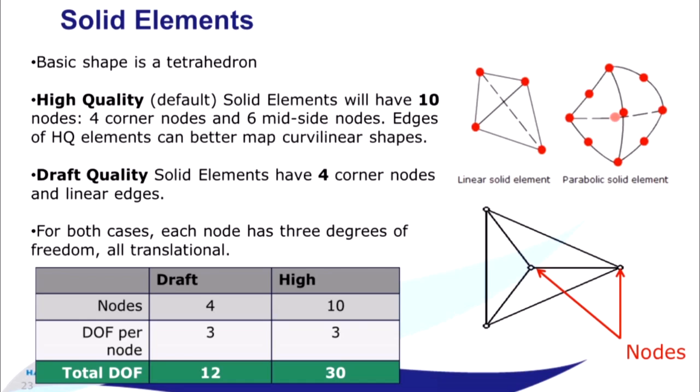That's really a parallel to the number of stress equations that get run for every element. So in this second order element, which is the most common usage, each element has 10 nodes, and each one of those nodes can move in 3 orthogonal translational directions, X, Y, and Z. And so we talk about this element having 30 degrees of freedom.